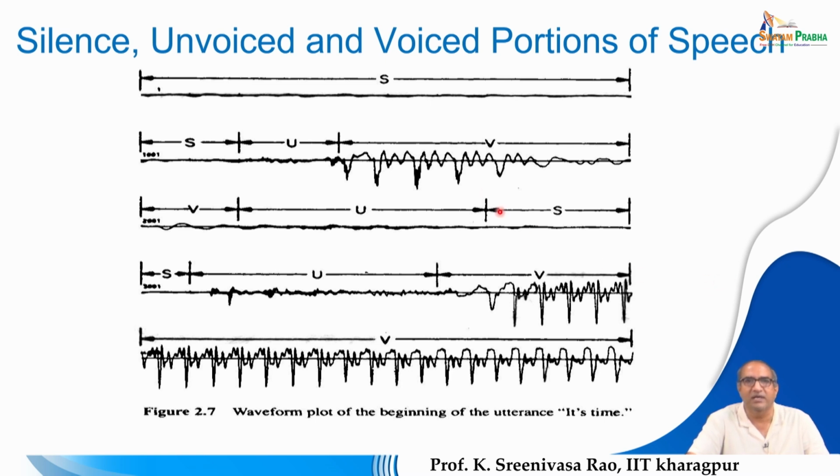So, directly by looking at the speech signal in the time domain, we can see whether the speech is due to voiced excitation, unvoiced excitation, or it is a pause where there is no signal at all. Beyond that we cannot discriminate much, because this voice excitation will be there for all the vowels. So by looking at this pattern it will be very difficult to say which sound the speech signal corresponds to.